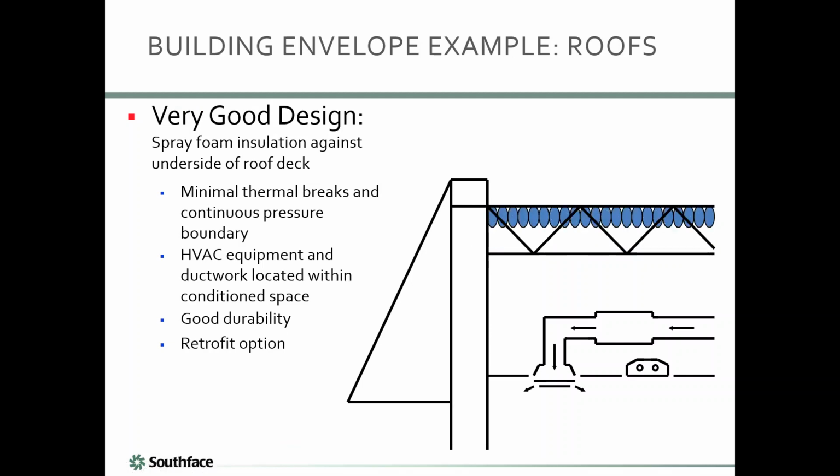A pretty decent option, and this might be the fix for a lot of those existing buildings, is to come back and spray foam from the underneath side. You're probably not going to meet the prescriptive R38, but this approach is really going to work. The ducts are all inside, which is of course good, and it won't fall off, and it tends to be pretty airtight. So I think this is good.